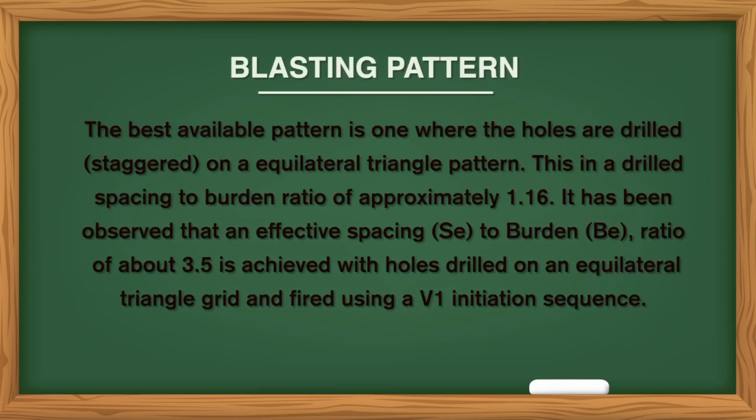The best available pattern is one where the holes are drilled staggered on an equilateral triangle pattern. This is a drill spacing to burden ratio of approximately 1.16.